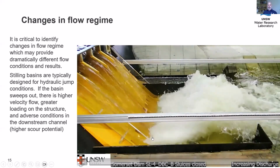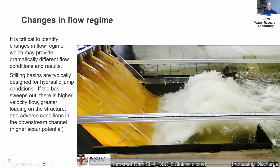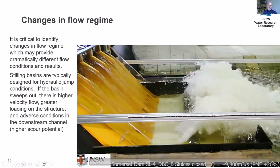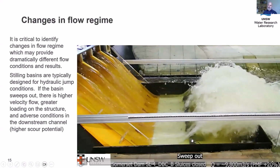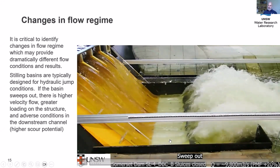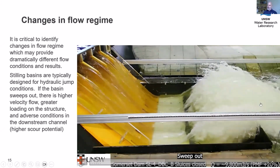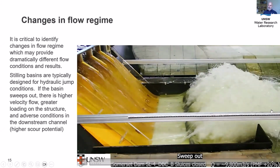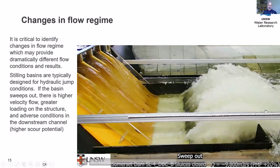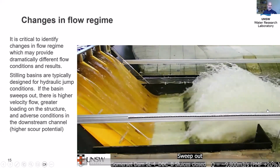So you transition from a hydraulic jump, and you'll see this go into sweep out. And so here, the loading on the baffle blocks is much stronger. We've got potential for uplift on the slab elements here, and also you've got this quite dramatic plunging jet down here, which is a real strong scour potential.